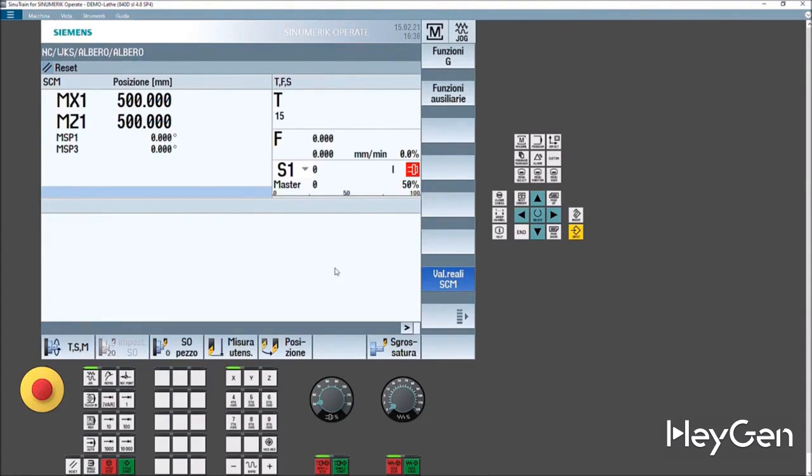However, if you program the same thing in ISO, the machine won't give you an error, even though there is a tap in the table, but you might have actually mounted an external tool. So there are some small precautions that make ShopTurn a bit less flexible at first, but then it becomes really interesting.